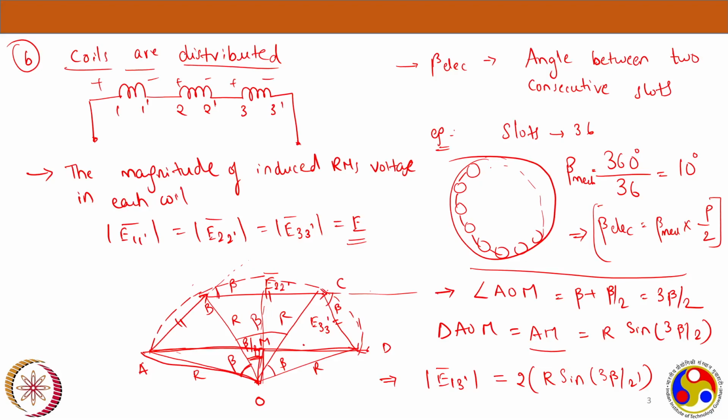It's not difficult, just a simple mathematical formula. Like that, in equal sides, if you know the exterior angle beta, then it will be equal to this interior beta as well. From that beta, we calculated the resultant in terms of radius. We got half of it as r sine 3 beta by 2, and the total resultant will be 2r sine 3 beta by 2. Still, we didn't complete the method yet. It's still in terms of radius, and we don't know the value of radius. R is still unknown. We will see later how we can solve this one. But now we got an expression for the resultant in terms of radius, that is 2r sine 3 beta by 2.